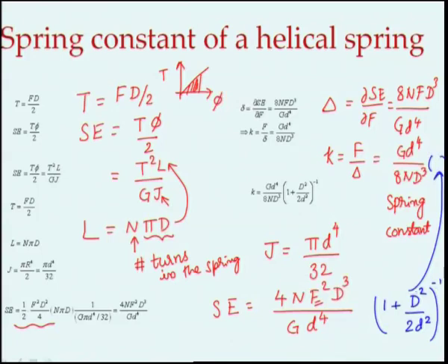Whenever we have this D by d ratio beyond a certain point, only then this correction factor becomes important, otherwise it is not going to be an important contribution to the spring constant. So, that comes because of the vertical shear force due to the force F.